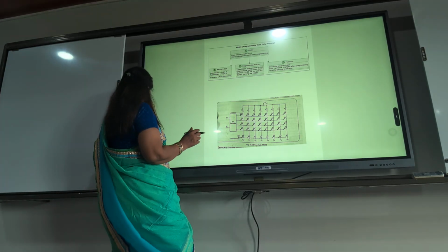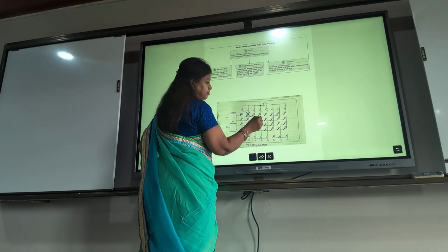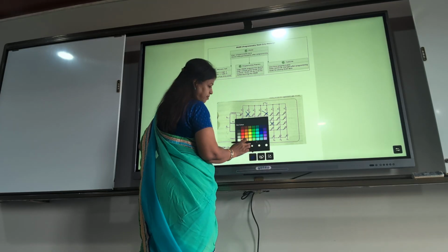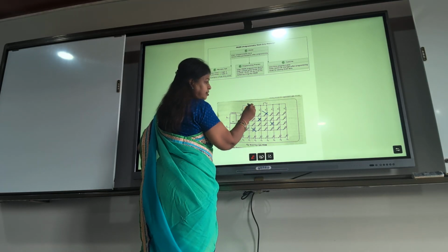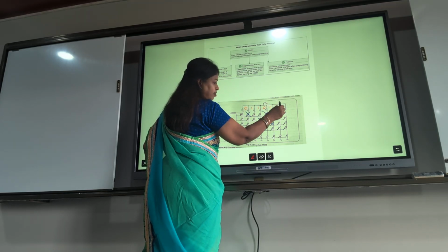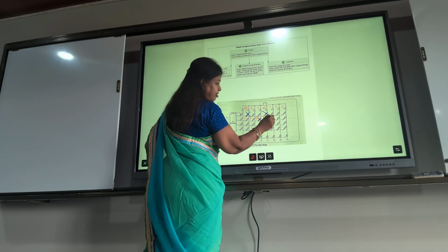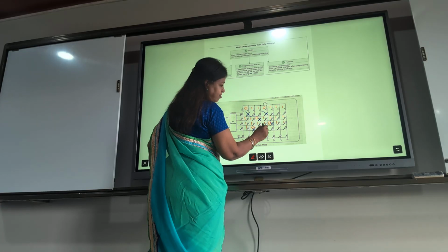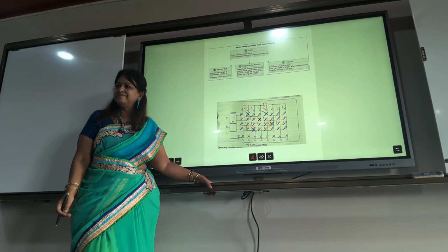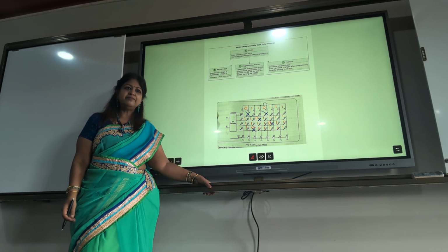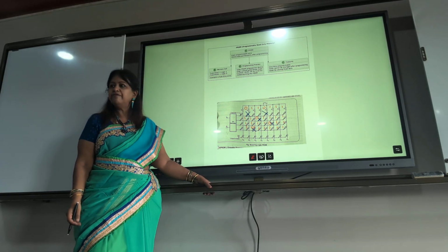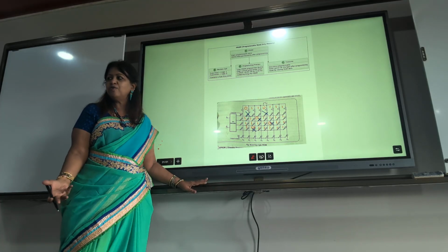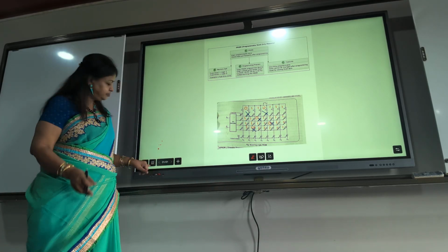The pattern stored is 1, 1, 0, 1, 1, 1, 1, 1, 0, 1, 1, 1, 1, 1, 1, 1, 0, 1, 1, 1, 0, 1, 1, 1, 1, 1. This is how I am programming in my company. Wherever you don't want the fuse, remove the fuse. That will become 0, because you can store only ones and zeros.